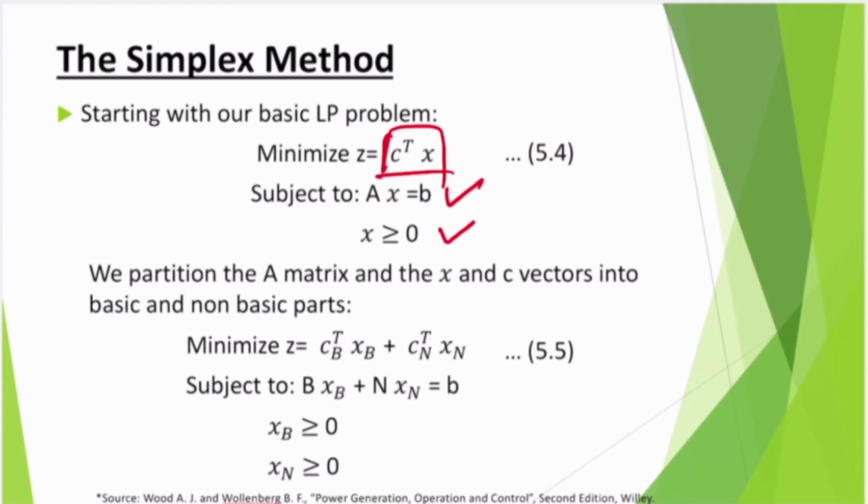And if there are many variables, then I can write: minimize the function, the first function, second function, you can keep on adding, subject to different constraints that need to be solved. So let's imagine that I have n number of power plants, and the cost characteristic of each power plant is linear. I have to optimize the total cost of the system. So I have to add many linear functions that need to be optimized with constraints such as P max, P min, etc.